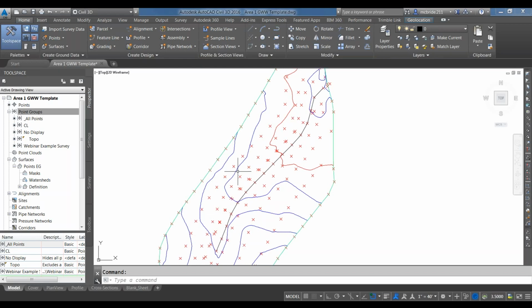As soon as you're done, you get back on the Gator and you can do a traverse survey all the way across there. So that was a good question. This isn't your typical survey for a grass waterway. However, that doesn't mean you can't do this with a cross-section survey. You just have to make sure when you do it, you take enough points outside of the grass waterway so that when you get into your design corridors and building surfaces, you have a big enough area to work with. It's a bit different, but it'll still work either way.